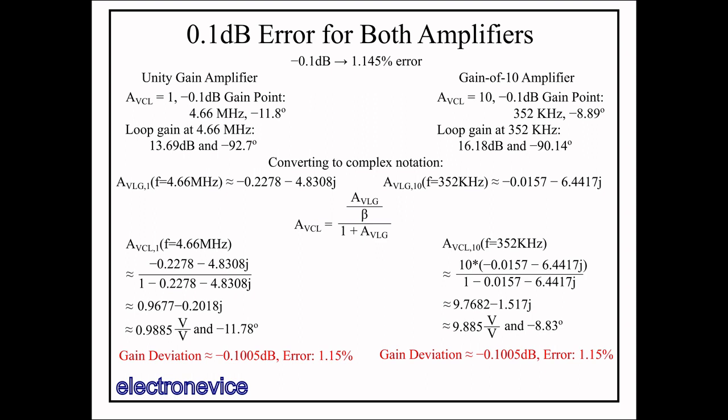One final thing to think about. Notice the phase in the closed loop gain. It is much different from the phase of the loop gain, which is good. However, its value depends upon the poles and zeros of the loop gain transfer function, even when they occur far from the frequency you're looking at, and the phase does change over frequency.